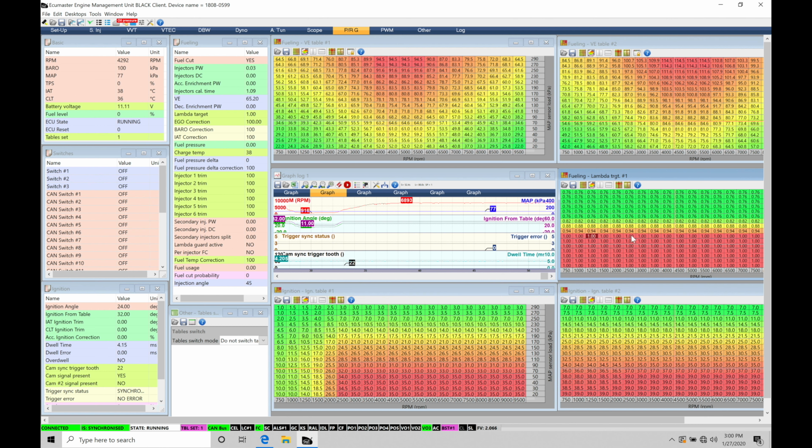We're going to have our target air fuel table. This is only going to be target air fuel table 1. And then our spark timing table 1, spark timing table 2, along with our graphical data. And then here we find our table switching parameter setup that we're going to go over here in order to actually activate this. So in order to make this work, we're again going to have a basic on-off toggle switch.